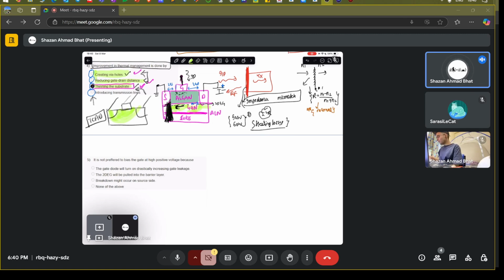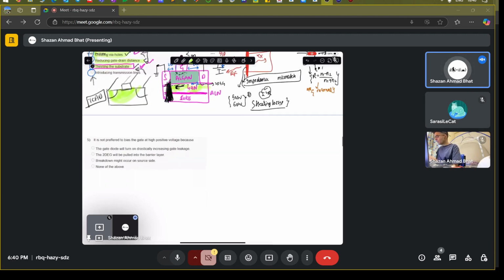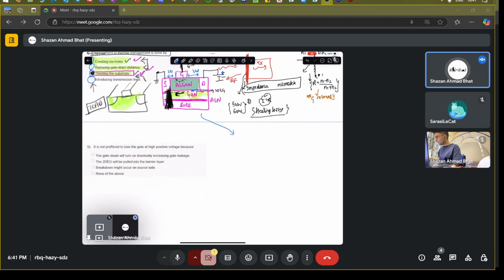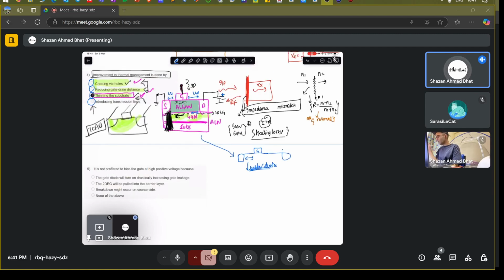And by simple physics, I remember there was research done in our group. A lab mate showed that if you modulate this gate to source distance, it gives better device performance and thermal management compared to having the gate exactly in the middle. Okay, so these are again open research problems, but they are all possibilities.